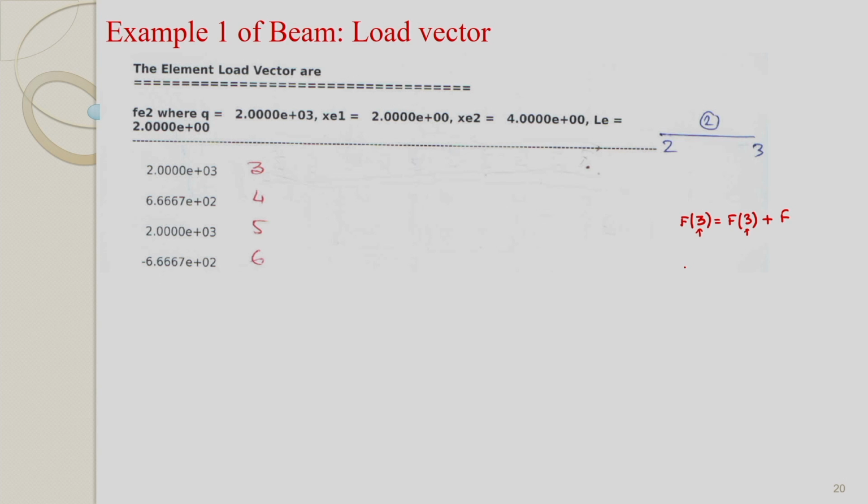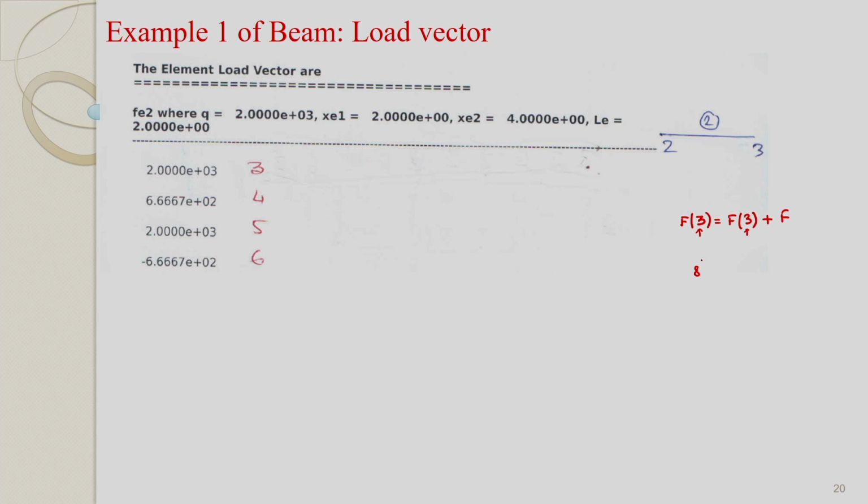So, in this case for the fourth node, the global degree of freedom associated with rotation is 8, that is coming from 2I, where I is the node number, which is 8. So, the 8th entry of the global load vector, there will be this M which will be added to F8.